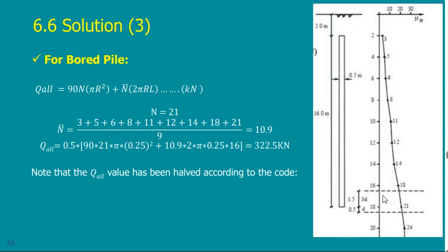value of the N values here at the pile tip, but not just at the pile tip. I go down D and I go up 3D, which is the diameter, 3 diameters of the pile. Any values given here, I will take the average of them. Here, by chance, it was just one value. Suppose I have here 21, and I have another value here, which is 20. Then if I tell you what is the value of N, it will not be 21, it will not be 20, it will be the average of 21 and 20, so it will be 20.5. This is the value of N.